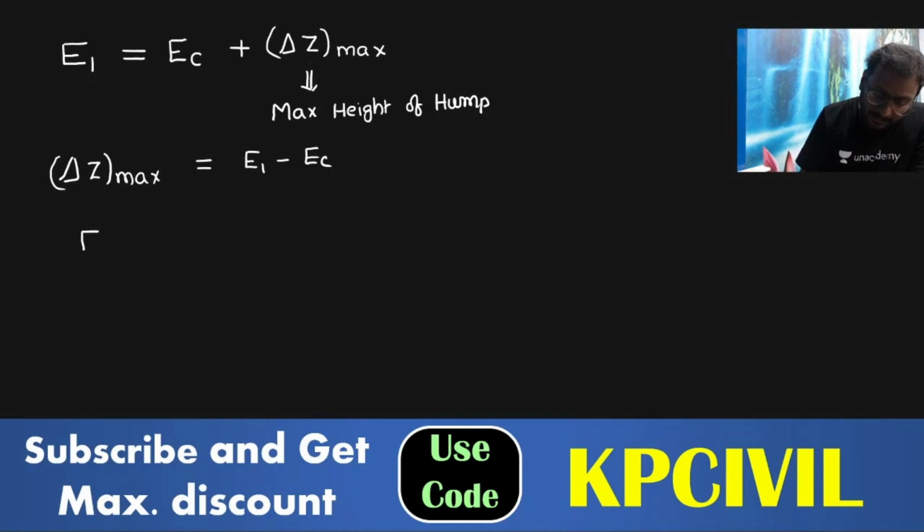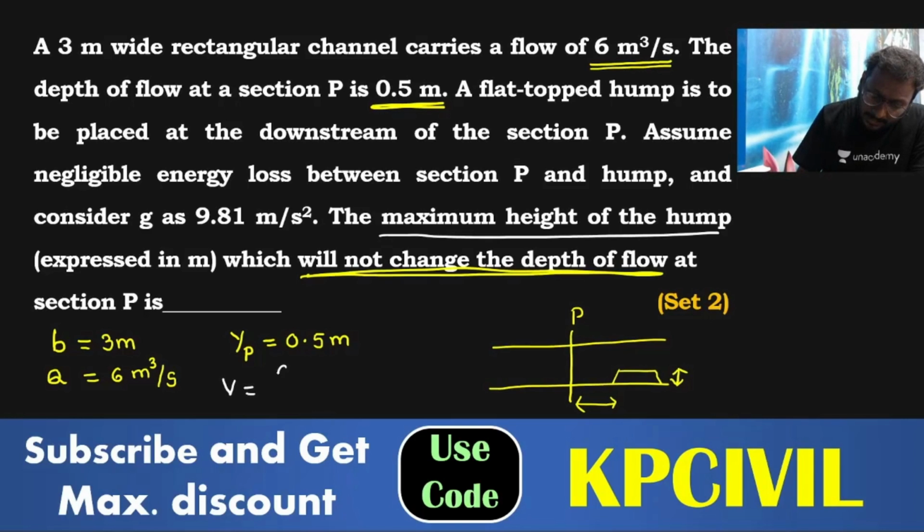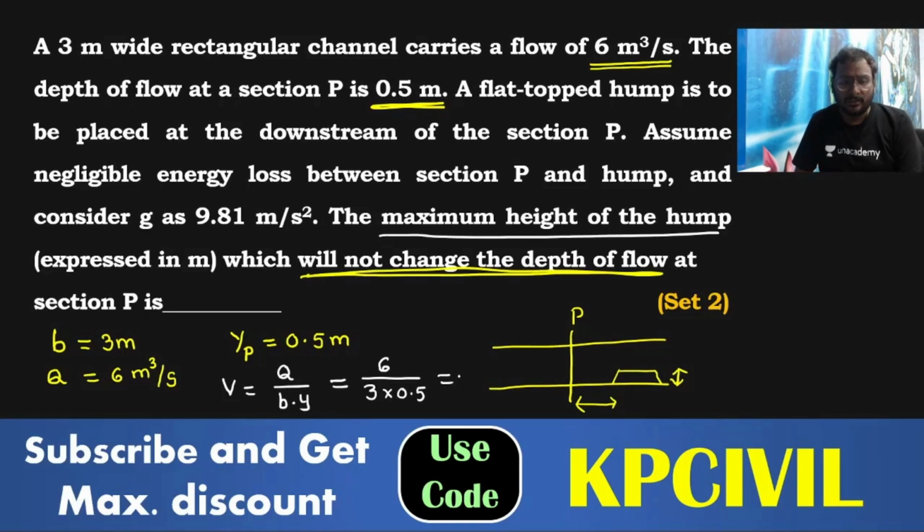So E1 is equal to Y1 plus V1 square by 2G. Y1 is nothing but YP, 0.5. And velocity is needed. Velocity is equal to discharge by area. Area I will take as B into Y. Velocity is equal to Q by BY. Q is 6, B is 3 meter into 0.5. We'll get the velocity now.